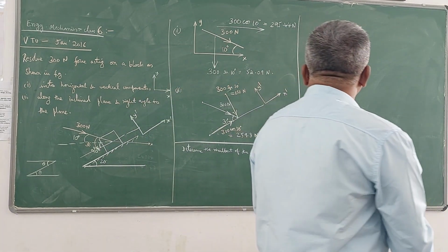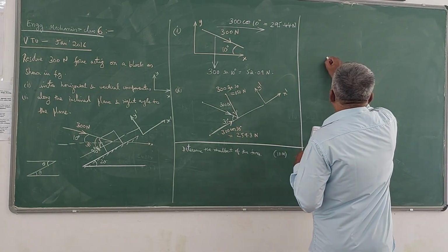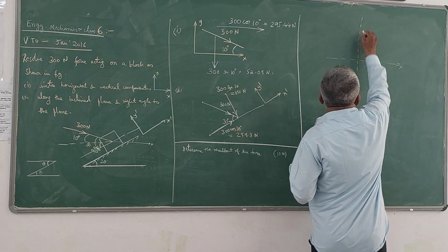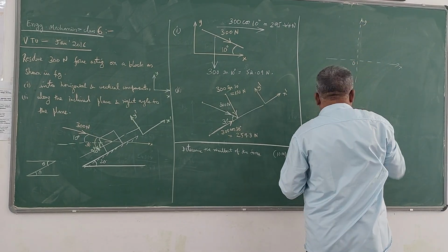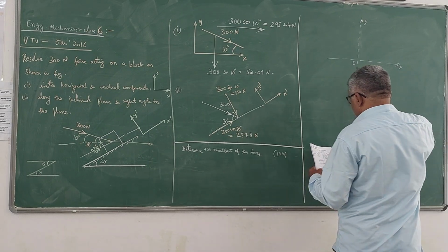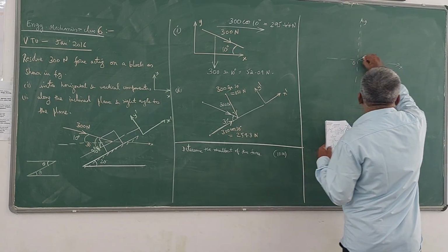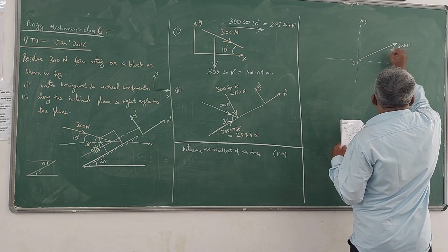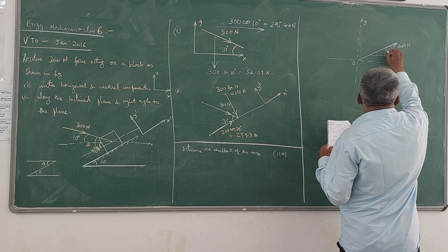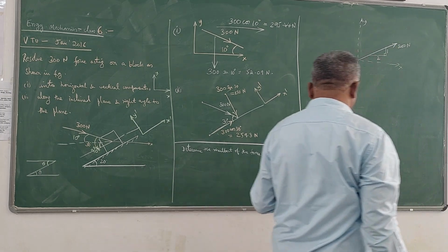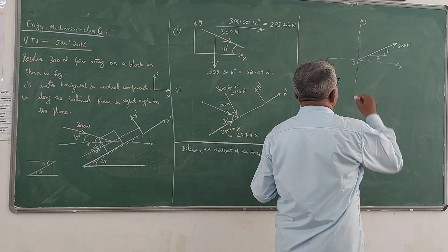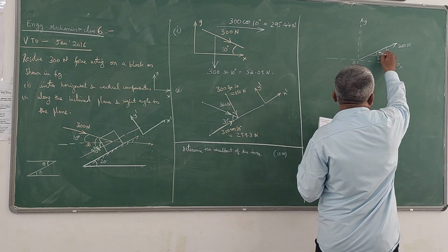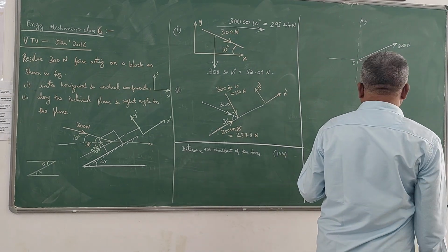So this is the figure which is given. X-axis is like this, Y-axis is like this. It is a coplanar concurrent force system. Origin is this. He has given the first force in the first quadrant like this, 200 Newton. Instead of giving the angle, he has given the slope. So one vertical to two horizontal. From that we can get the angle. Suppose we take this angle as theta 1, we can always find out that angle theta 1. So tan theta 1 we can find out.